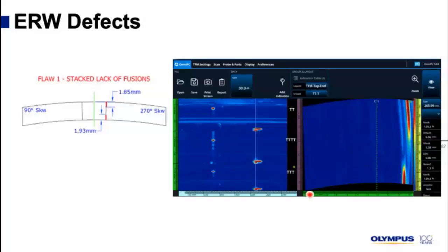Keep in mind also that the more bounces we have off the back wall, the more the geometry will affect which waveset we need to select. And so 3T for this geometry and this type of defect might not be the same as on flat. I might not image it the same way. That's why it's important to use the modeling tool for every kind of geometry that we are using, for every inspection.